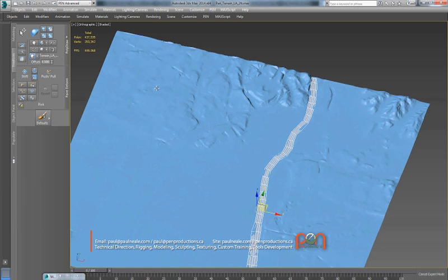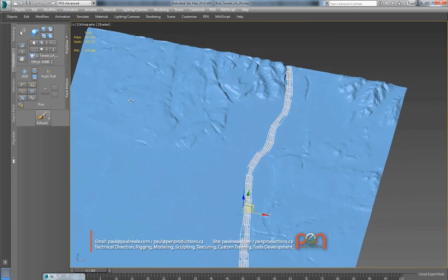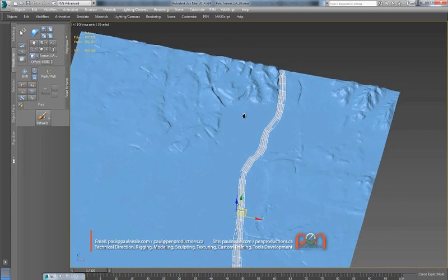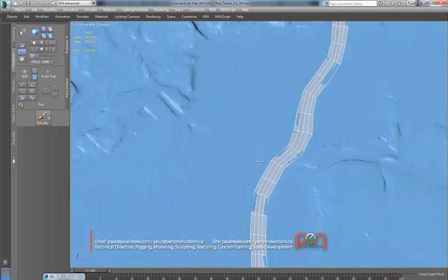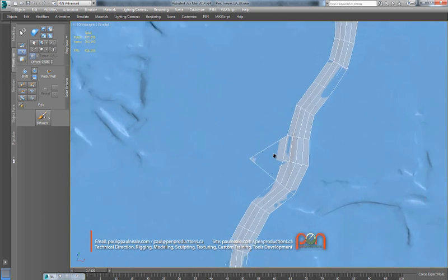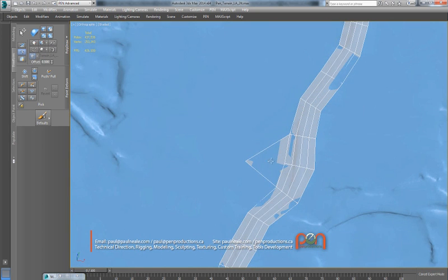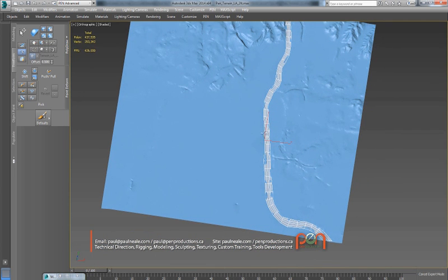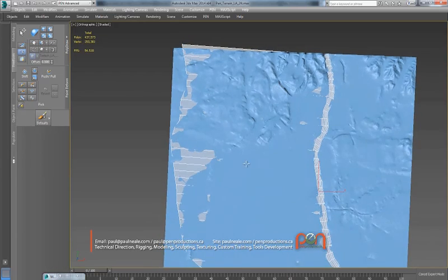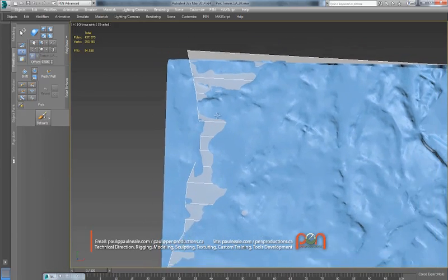And so let's do that with another freeform tool. We can use the topology tool again, but what I'm going to do is do it real fast and simple. I'm going to use a tool called extend. What extend will do is create a new polygon anywhere I grab a vertex, or if I hold down Shift, I can grab and just pull out a new quad from an edge, or if I hold down Control Shift, I can pull out an entire edge loop here. So I'm actually just going to crank that all the way over to the other side. Make it real simple and fast to do this.